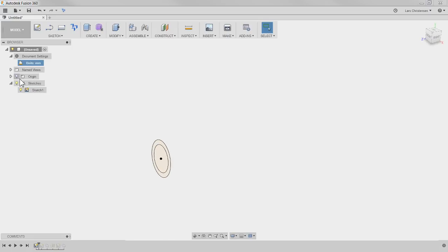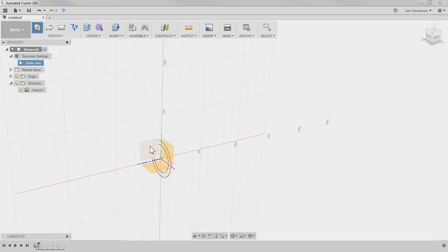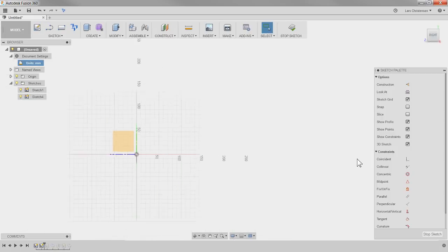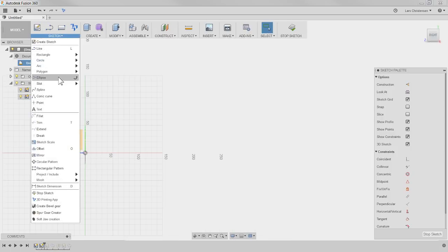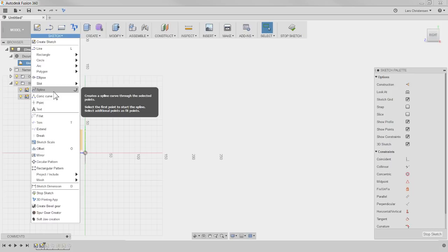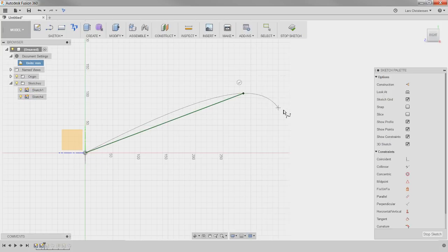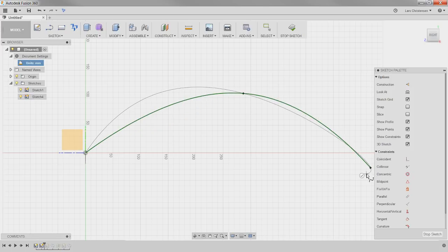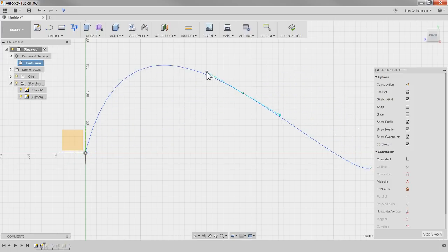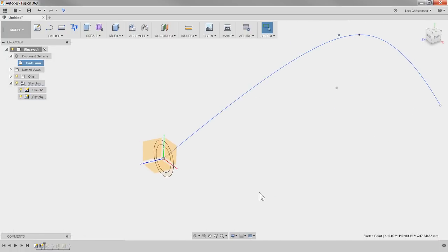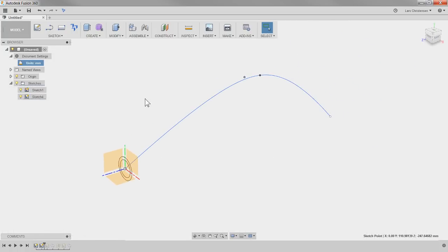If I create a new sketch, so now we have it down here in the bottom, and create a spline instead. Before, when I created the pipe, I just used some lines and arcs, which is great for pipes, but if you're doing something like wires, you maybe want to use a spline. With splines we get these handles where we can make some really neat shapes, and we can use these splines also as paths for our guide curves.